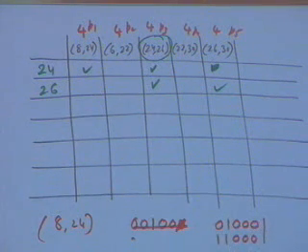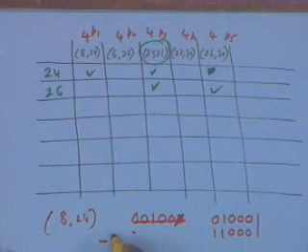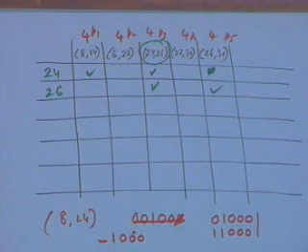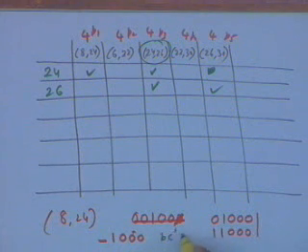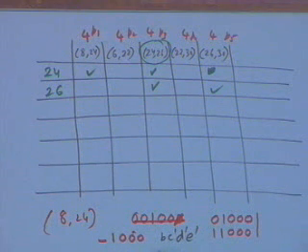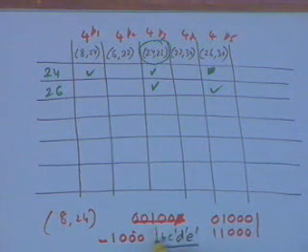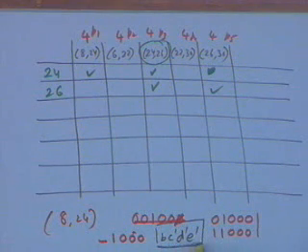So 8-24 is going to be nothing but dash 1 0 0 0 0. So now what is the expression that will realize this? This is B C complement D complement E complement. A is eliminated. This is the expression, and the cost of this expression is 4 because the number of literals is 4.